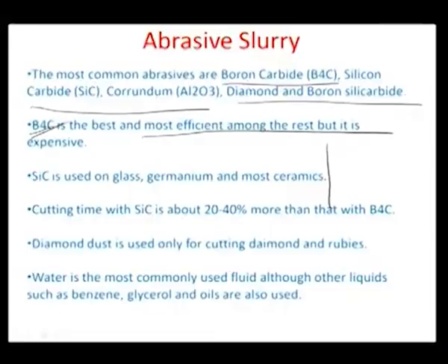You saw earlier that in comparison to normal silicon carbide, the boron carbide would have a higher material removal rate with respect to, let us say, concentration. And the average roughness of course will be more, so that there is more cutting action. So this is B4C, this is SiC. So this was how Q would vary with concentration.